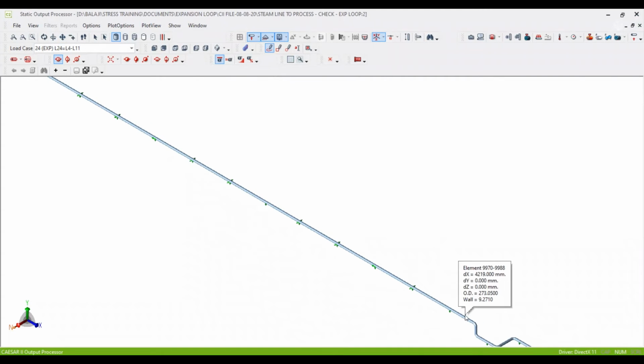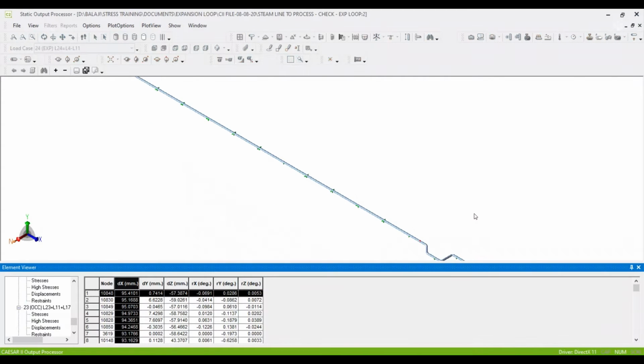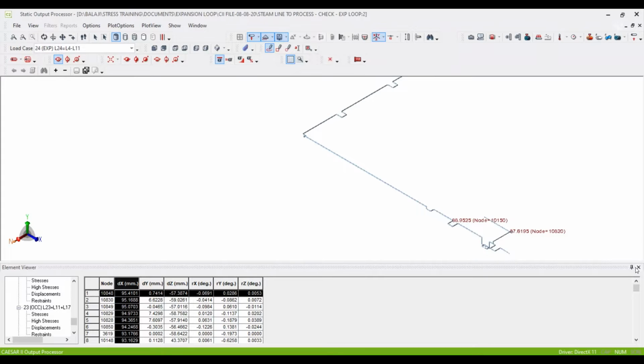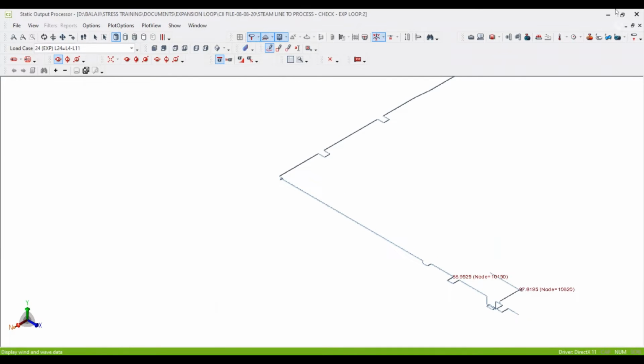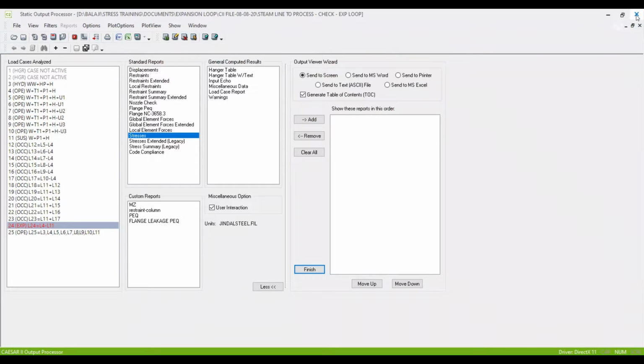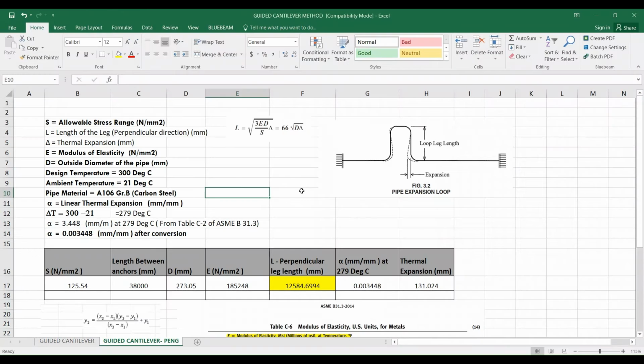If you check the displacement here, see, the displacement is 95 mm. So it is within the allowable only, within 100 mm, in the axial direction. Okay, don't go like this. We should use only one limit stop in one direction. Sometimes it will not show failure also, if you use one or more limit stops in one direction.